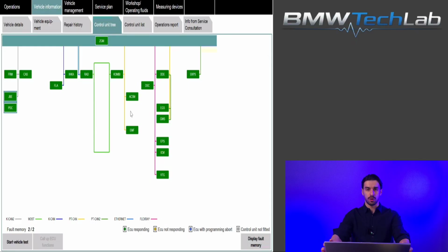For the system to work properly, you need to have basic things, and one of them is the wheel sensors. The car needs to know the rotation of the four wheels. Otherwise the control unit will get confused, and in some cars you will get these symptoms.